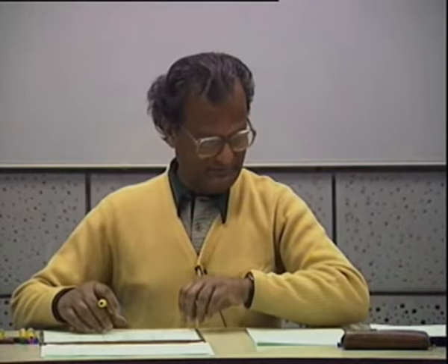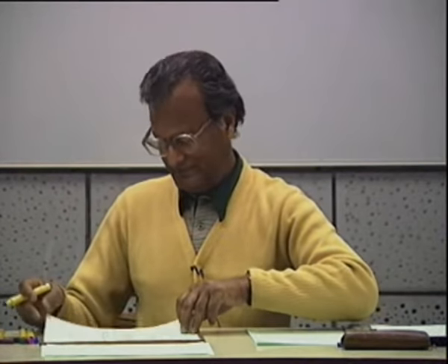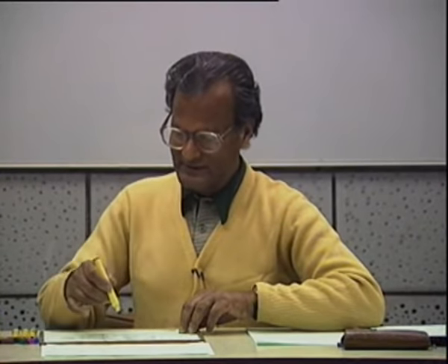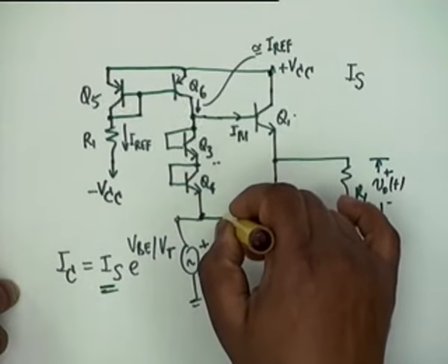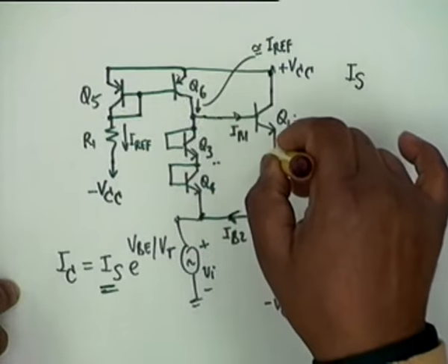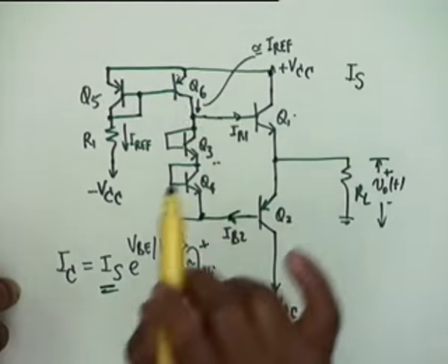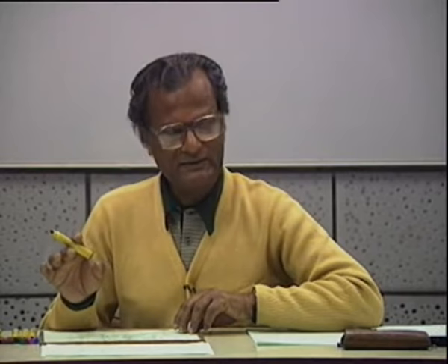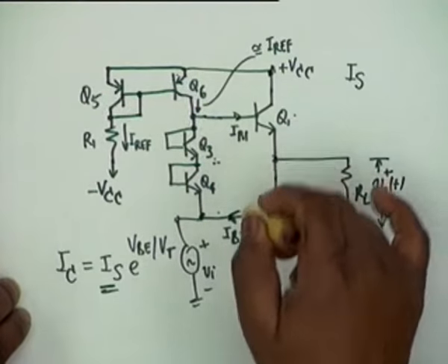Okay. Now going to an analytical formulation of the whole problem, what we want is that VBE3 plus VBE4 should be equal to VBE1 plus VBE2. That this is a balanced circuit is a different matter, but analytically we shall bring that balance equation later. Our simple KVL is that VBE3 plus VBE4 is equal to VBE1 plus VBE2.